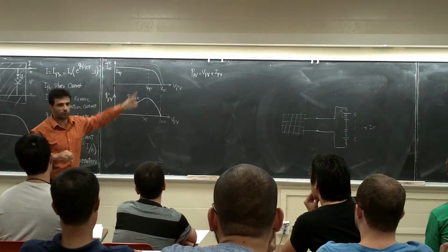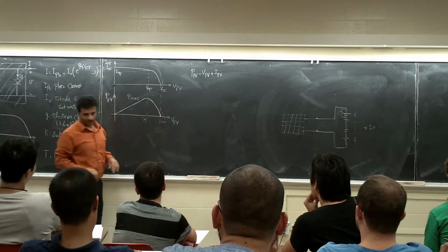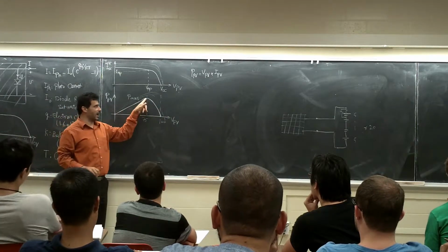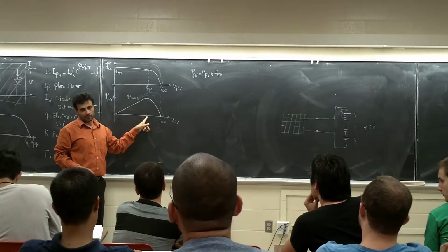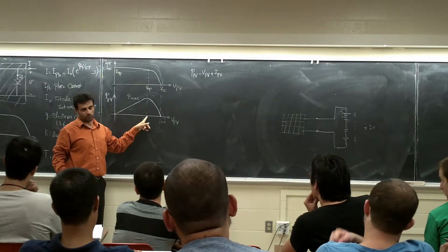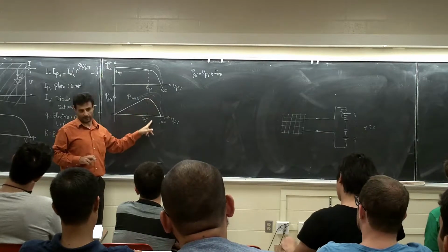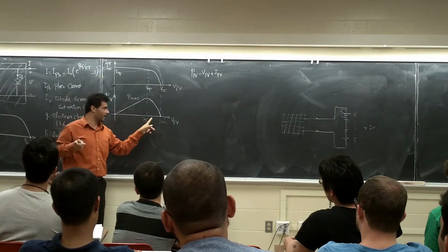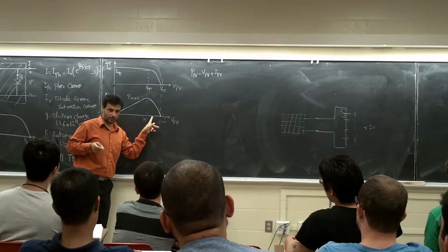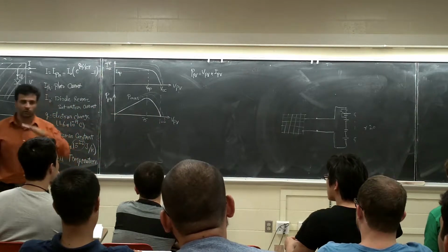When you have a bunch of those curves, you have a bunch of these points also, right? Maybe at 10 a.m. you should work here. That's the best place to be. But at 11 a.m., I don't know, you have a better sun. You know what I'm saying? So we're going to be here. Your control system, your algorithm, will tell you, hey, now you should work at 80 volts. Now you should work at 90 volts. You want something automatic, so change this one, track this one.